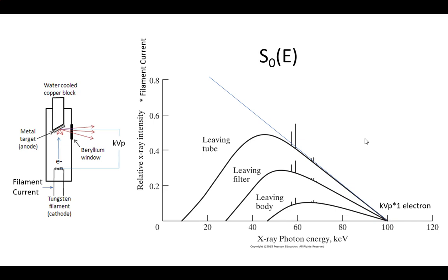Yeah, it's really close. The other thing is, if you take that distance between the valence electrons shell and the next shell up where it can start moving about, there's an energy level that kind of sits between these. Right? This is called the Fermi energy. Right? So if the Fermi energy is really close to the conduction band, it's way up here, that's a really good conductor. Because what that's saying is, this is the amount of energy due to temperature.